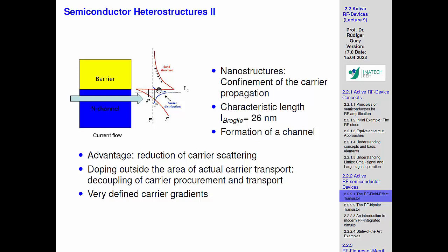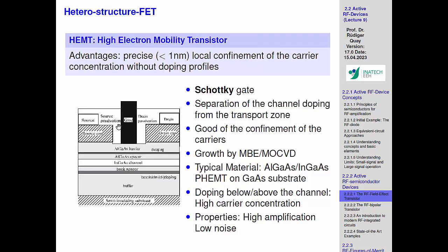And it tells you why we need these quantum effects: only because of the separation of the carriers which you transport from their doping remnants, as we say, the remainders where the silicon is still sitting without the electrons. Only this enables this performance. So this is physics. And why does it work so well? Because the carriers tunnel, they stay here. And the modulation efficiency, as we say, so how well can we modulate those carriers in the channel? So how easy is that?